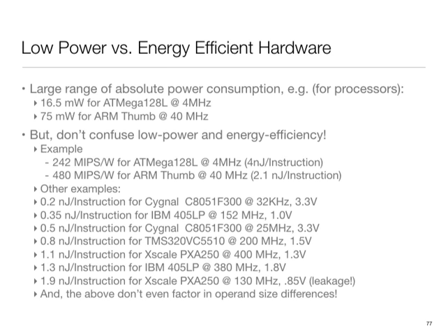So in some applications, the low-power part may indeed be sufficient, and you may also be peak power limited, namely you care about how much dissipation is happening. I refer to applications like implantables. But if battery life is an issue, then the energy consumed becomes important, and more often than not, the choices are such that bigger, more sophisticated things tend to be more efficient from an energy perspective, particularly when doing bulk work, whereas simpler things tend to be lower power and are better off doing small tasks. So this simple versus complex difference plays out.